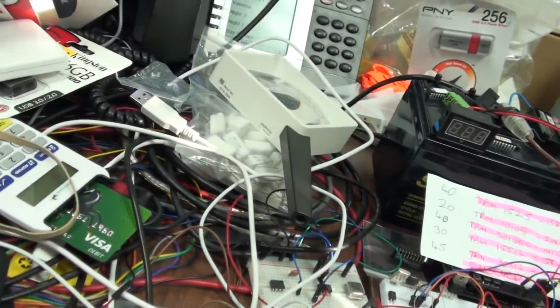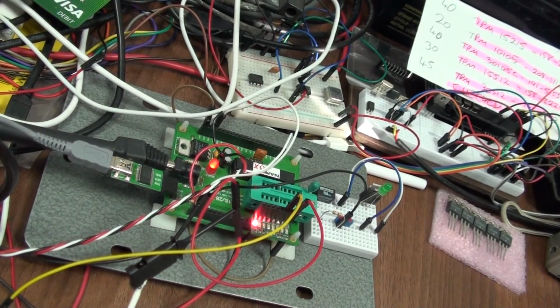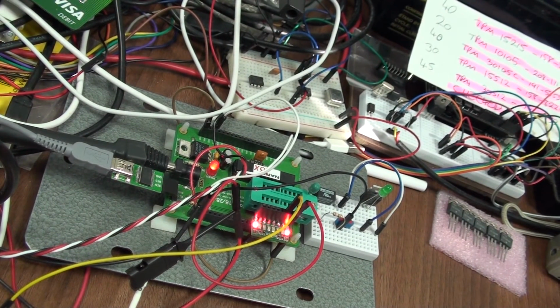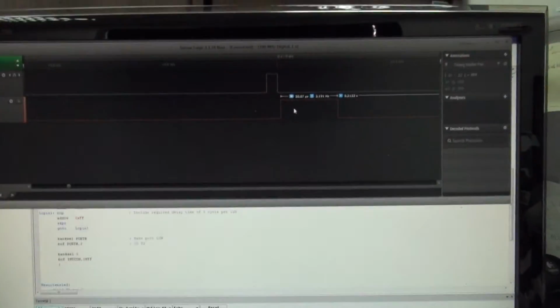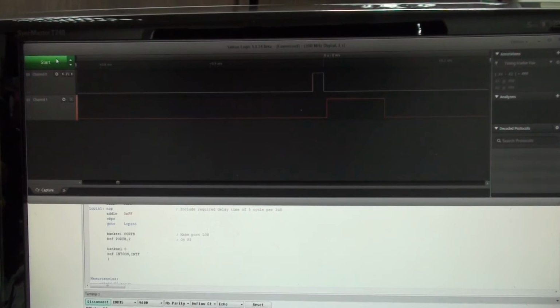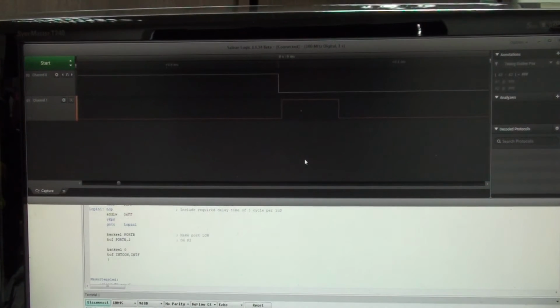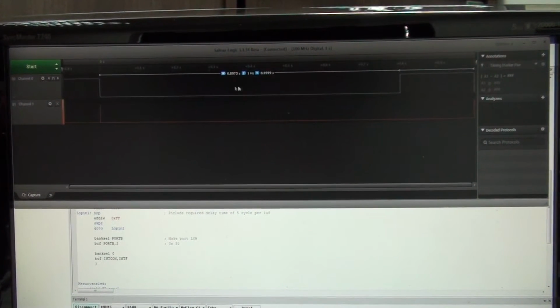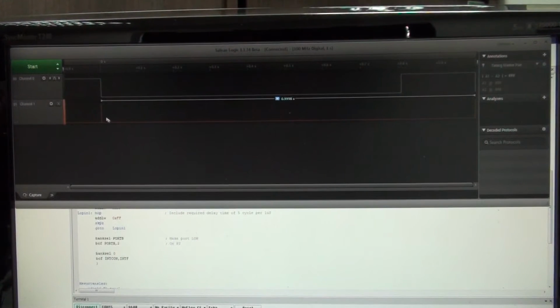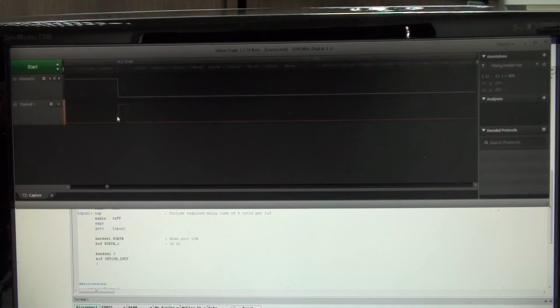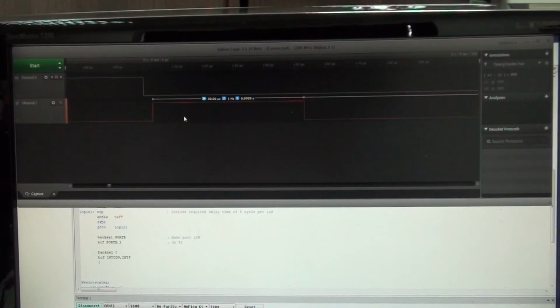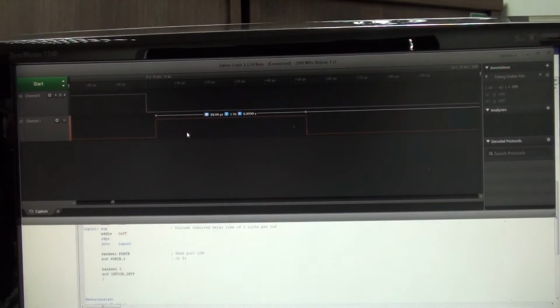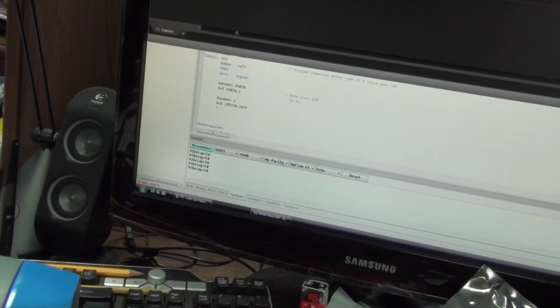So back on the hardware again, you can see now P0 is pulsing 20% duty cycle and 1 Hz. So if we go back to the logic analyzer and I do a refresh on that, that's just calculated, we can now see that the pulse is coming in at the top, which there are 1 Hz, and the pulse width coming out at the bottom is 50.6 microseconds, because that's what the rate the potentiometer is set up at the moment. That's still coming in as 50.